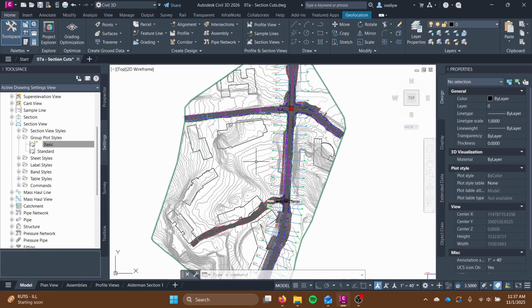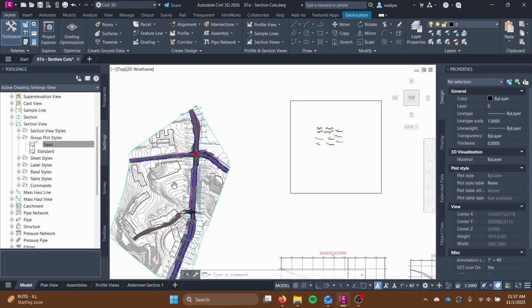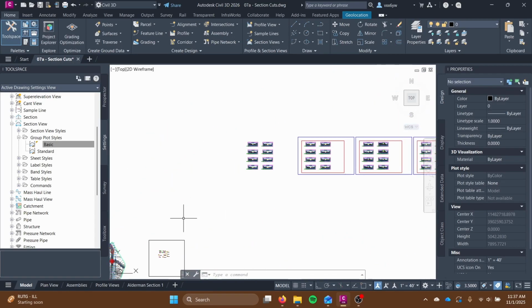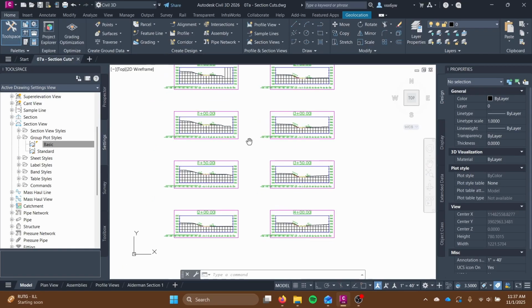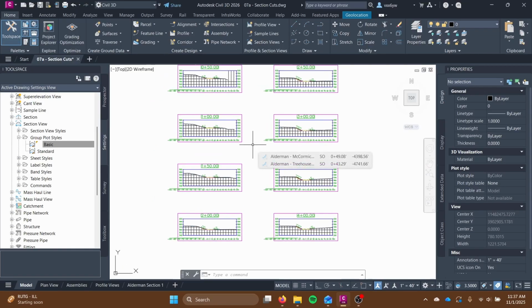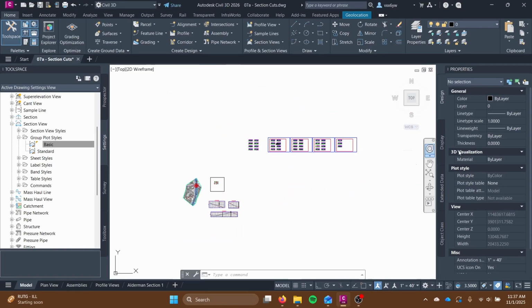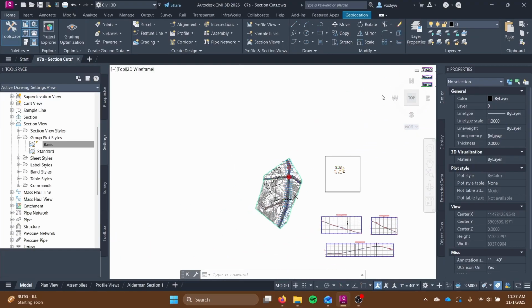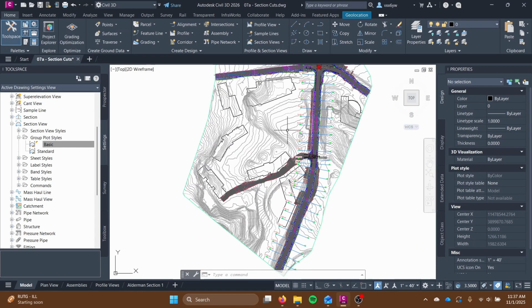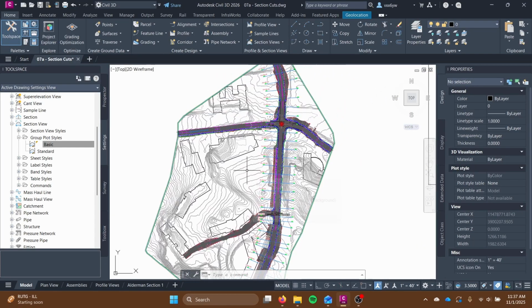They're both shorter roads, so there should be less sections for them. And if you remember how I changed my spacing interval to be 25 feet along curves, if you keep that as 50, you'll also have less of these. So that's up to you. But you need to submit your section sheets with your full plan set as part of deliverable 7.